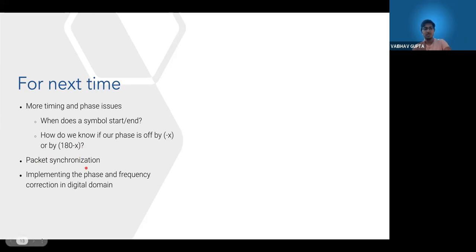And as you'll see, once you've implemented things like phase and frequency correction in MATLAB, you'll realize that not all of it, as it's implemented in MATLAB, translates as easily into a microcontroller. So like we did the first time around, where we first had you use MATLAB functions for a low pass filter, and now we'll move to digital filters, similarly, we'll first start by relying on MATLAB to develop an intuition for how phase and frequency correction work, before we then develop a discussion on how we would do that in the digital domain.